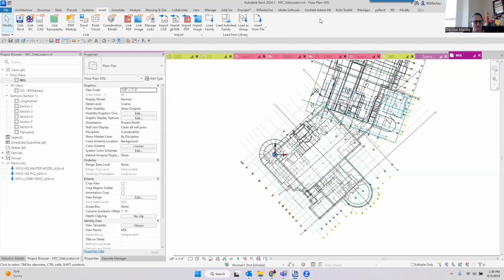So we're going from shared coordinates to shared parameters. I'm going to screw that up. Technically you need to make it a shared parameter if you want to tag and or schedule. If you just want to schedule something, then you're going to be just fine creating what's called a project parameter. But if you want to be able to create a tag and a schedule, then you need it to be a shared parameter.